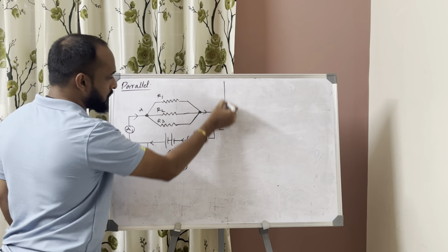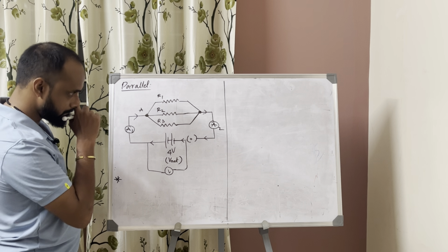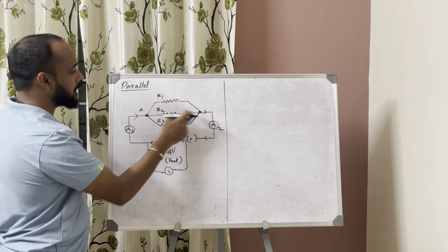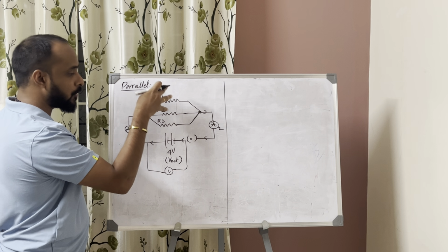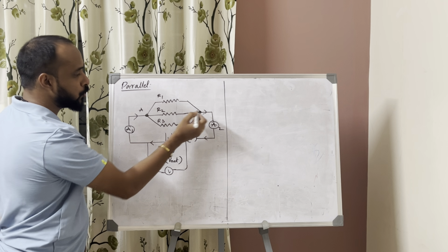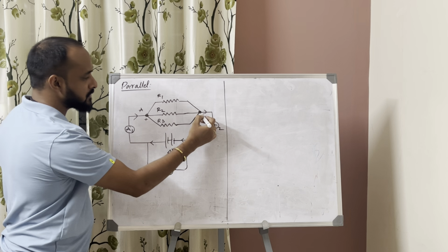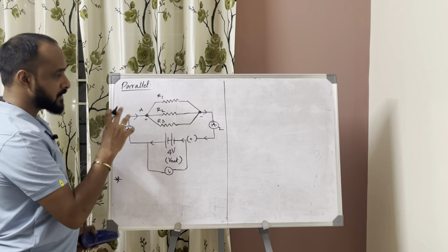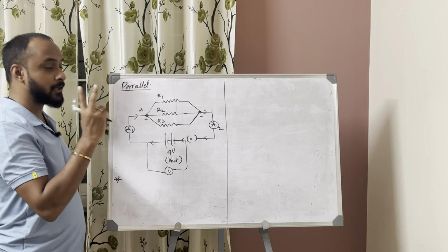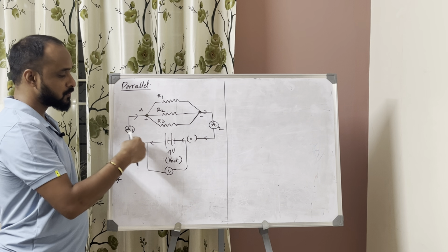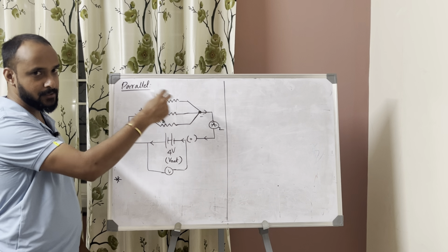Now, talking about the general properties of this circuit, as you could see, how many electrically common points do we have for this circuit? We have 3 resistors, and for all the 3 resistors we have 2 electrically common points, one connected to positive, the other connected to negative. So generally, if you have only a parallel circuit, you will have 2 electrically common points. One is towards positive, one is towards negative, where all of them are connected together.